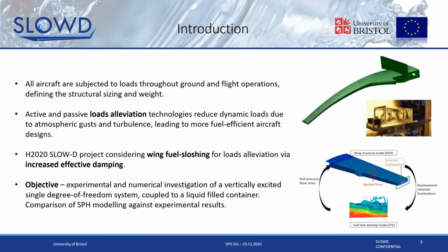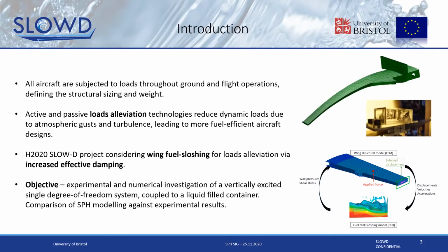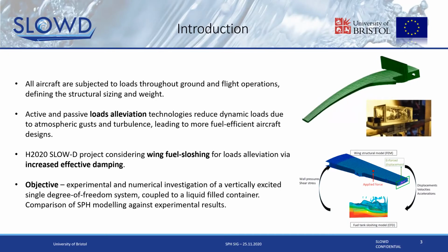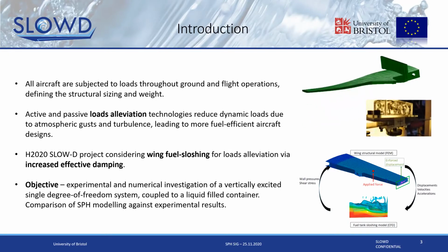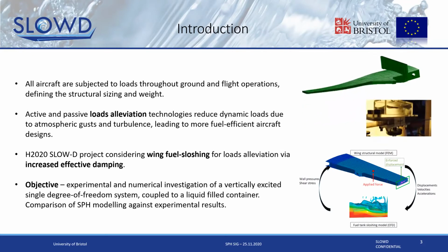So the objective of this SLOD project is actually to understand and quantify the induced damping effects you get from this sloshing fuel in aircraft wings, and provide validated methods for modeling it and experimental investigation as well. So this is to take into account the actual effects of fuel sloshing in the aircraft design. So hopefully we can design lighter wings, more efficient aircraft as we go on.